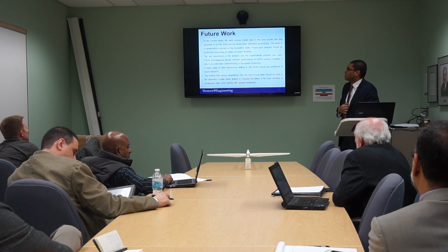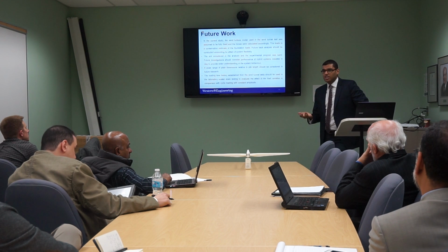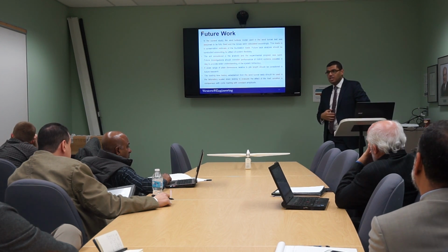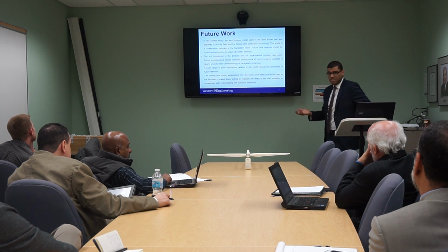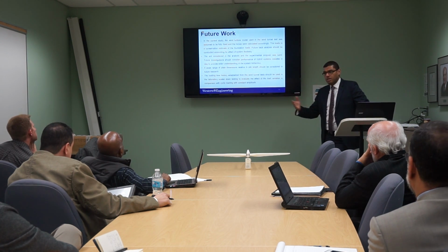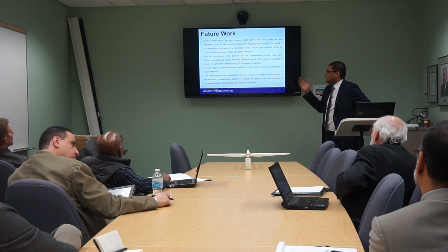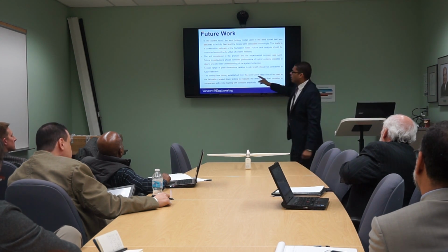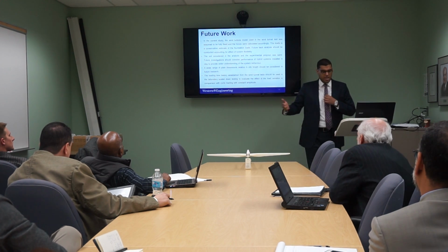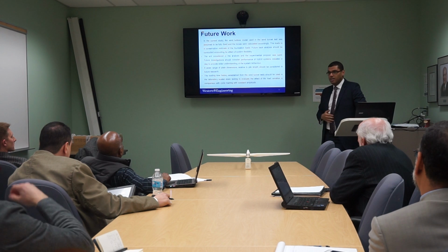For our future work, at the beginning in the wind tunnel, we assume that foundation is rigid, although it's not actually rigid, so there is some flexibility. So we need to see the effect of this flexibility in our calculated loads. We just study on sand, so we need to see the effect on clay. We need also to have different combinations between blade diameter, pile length, pile diameter, and also in the future we will be able to apply the actual time history on our model instead of just applying cyclic load.